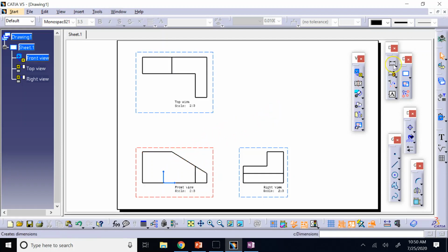So you activate it, then you click on this command, and here you are going to draw the side view of the auxiliary plane or projection plane. And to do that, you make sure that plane is parallel to this edge or on the top of this edge. So here I draw a line that, as you can see, is coincident with this surface.